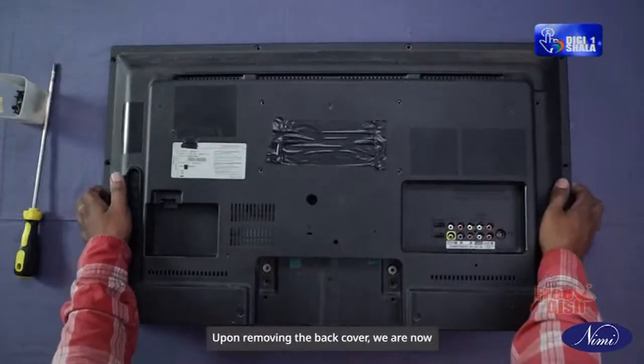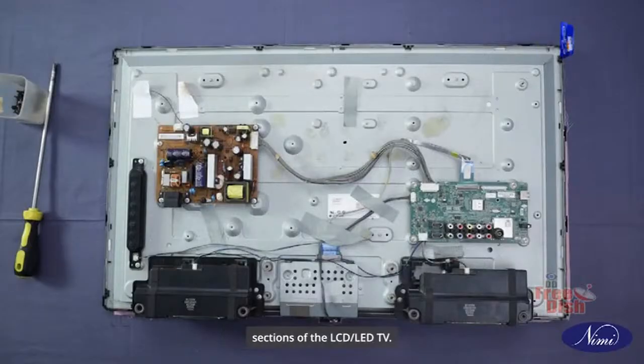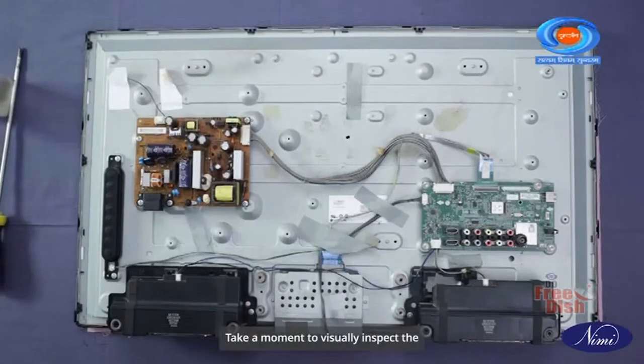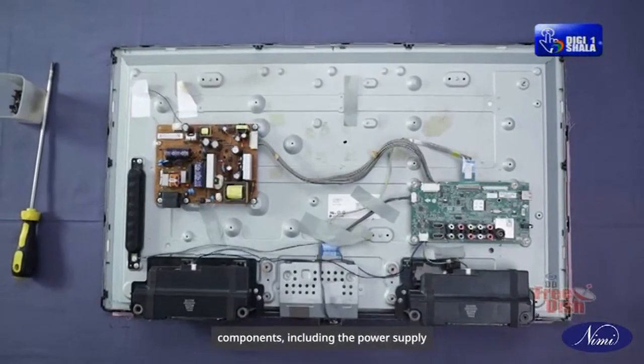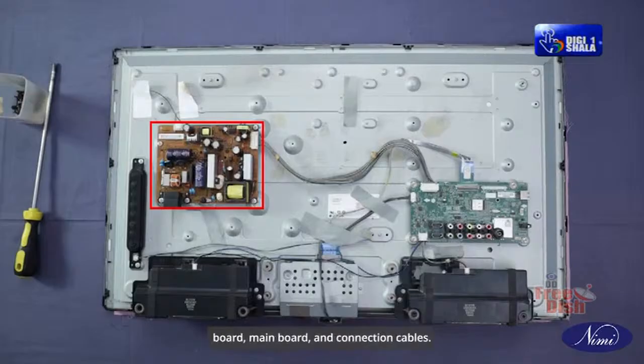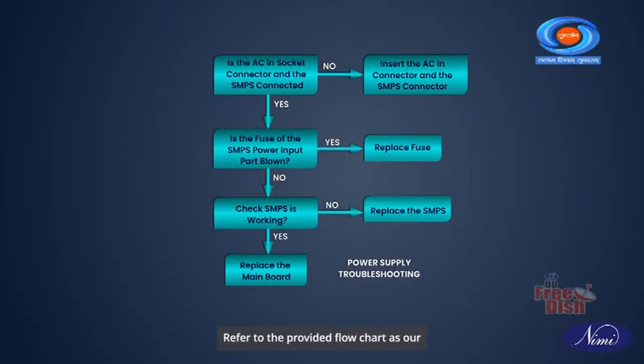Upon removing the back cover, we are now able to observe the various internal sections of the LCD or LED TV. Take a moment to visually inspect the layout and condition of the internal components, including the power supply board, main board, and connection cables. Refer to the provided flowchart as our guide for systematic troubleshooting.